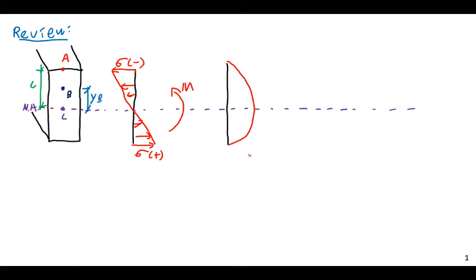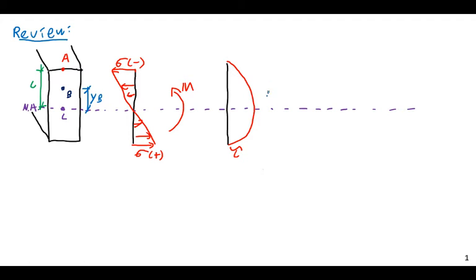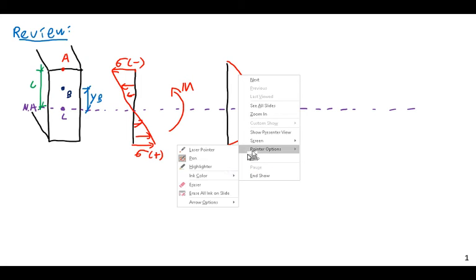Hey, that's not so bad. With a shear stress tau here, all of the shear stress will come together, the vector sum of all their stresses multiplied by dAs. If you did the integral of that, all of this would come together to form our shear vector V, the shear from our shear and bending moment diagram. Now, from this, we can actually see a few things about the state of stress.